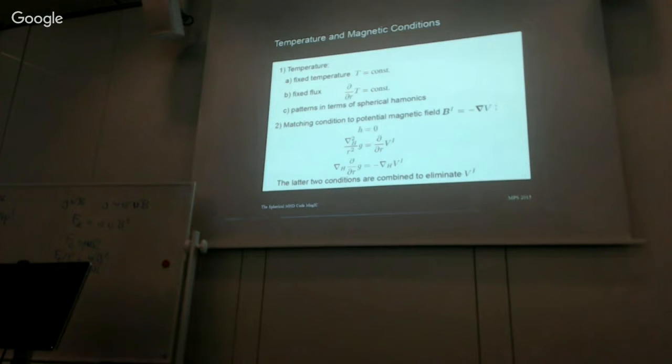Okay, you just say, use this boundary condition, and you don't have to fix the actual temperature, because it's just a way of rescaling, actually. The alternative is you fix the flux, and so the radial derivative. So K, the thermal conductivity, times this radial derivative would be the heat flux.